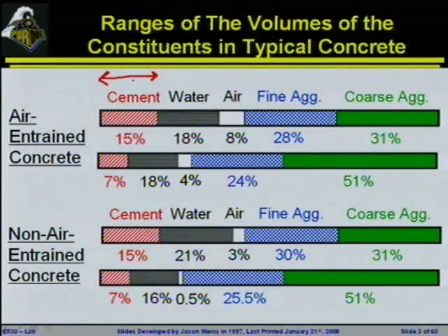It's the component that's actually doing something. It's the glue, it's the binder, it's what we're changing when we add supplementary materials. It has the porosity, it controls the strength. It's a really important overall constituent material. Water will make up another important part of this, and again, it goes into making the binder. It goes into defining things like the workability of our fresh concrete.